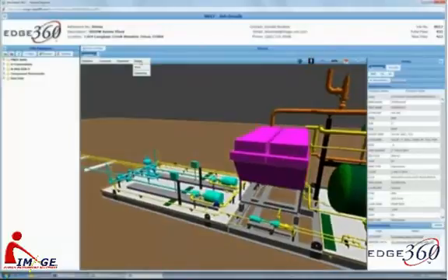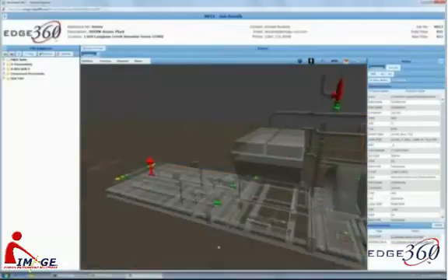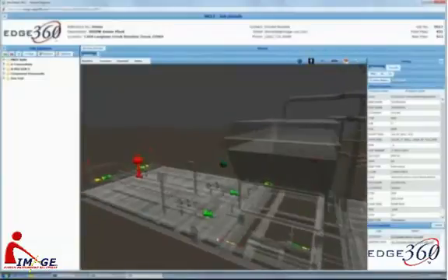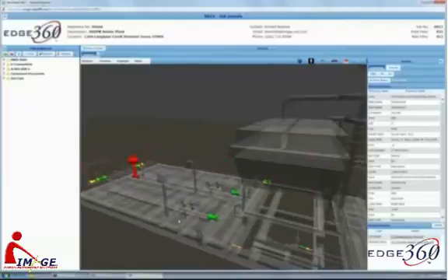But I can also do other things like integrate the knowledge that's embedded within the P&ID and visualize that by doing things like showing the normal states of the valves. So you can see that green is open, red is closed. That is very convenient to help you visualize. I can also go in, and I'm not going to do it right now, but I could go in and create alternate states where maybe startup, bypass or blowdown or whatever, and visualize those valves.